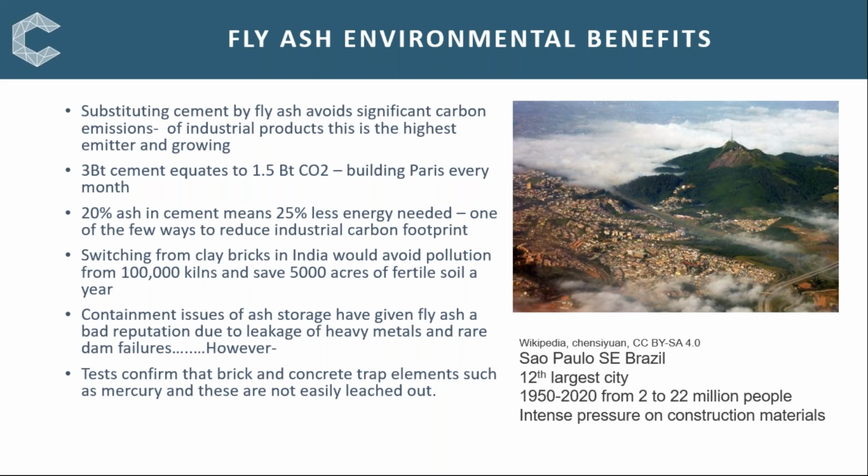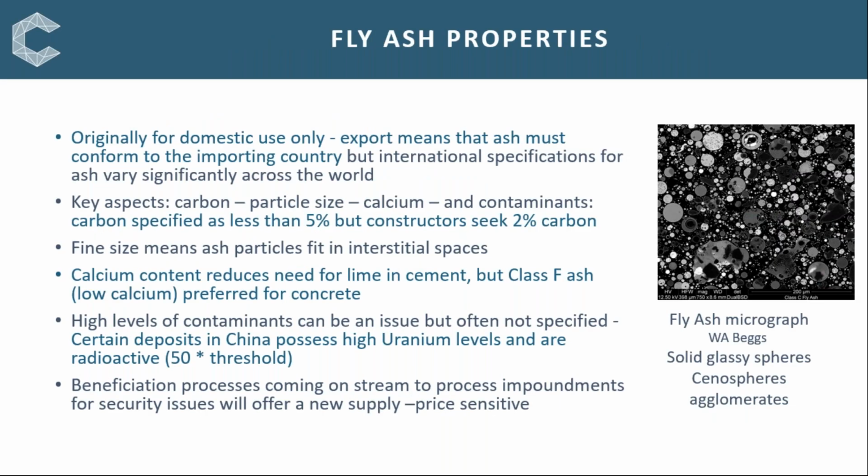All right, and now turning to some of the ash properties. This micrograph shows the perfectly round spheres of fly ash. Most are solid, but some shown here are hollow, and these are termed cenospheres. These are highly valued products and are incorporated into fillers. Some ash particles are agglomerated and become more like bottom ash.